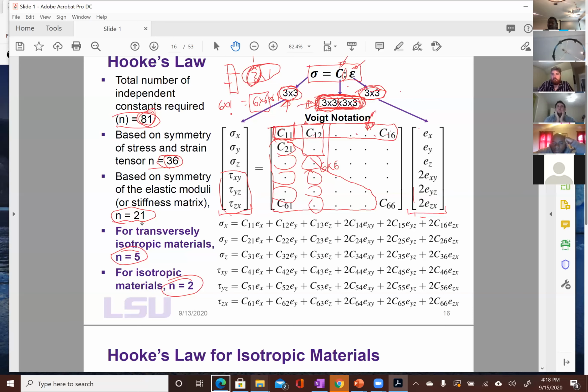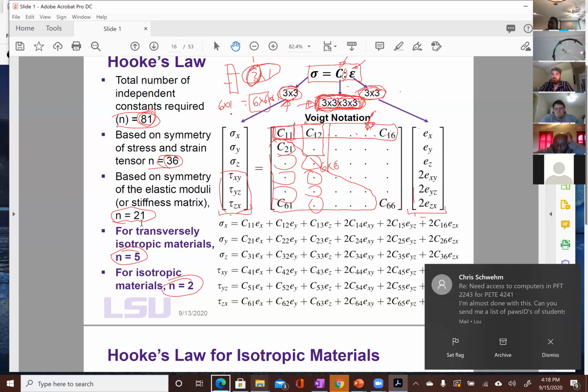So it's a stiffness matrix. An example could be Young modulus in the x direction. Another example, Young modulus in the z direction. Young modulus in the y direction. Then you go to Poisson ratio, in the x direction, in the y direction. And you will see examples of those on the next slide. But definitely not for 81 components.